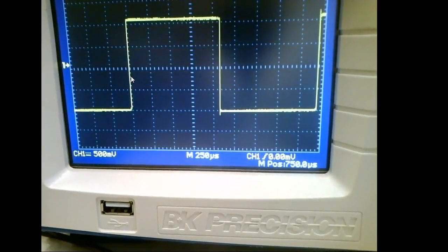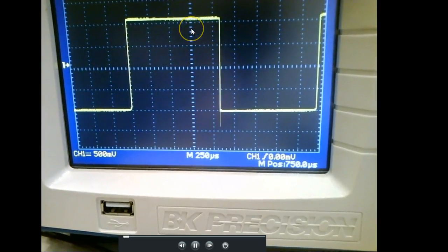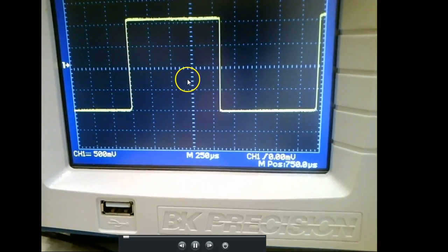So what did you get for them, Mr. Rick? So it's not 4.5, what is it? It's 2.1 volts. For what? Time or amplitude? The volt. Well, the way I showed you, take the number of major divisions, right? And then count the number of minor divisions. If we count in ones, then each minor division has to be worth 0.2. So I'd say 1, 2, 3, 4.2. Then I would multiply that by 0.5, which is 500 millivolts.